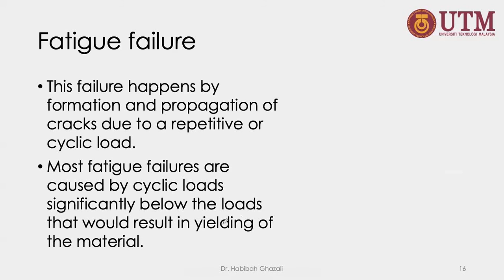But for cyclic load, for example, a timing belt, your car service. The engine keeps rotating round and round, isn't it? Cyclic load. So there is a limit. After 100,000 kilometers, there is some service. The kilometers indicate the cycles. They know after this number of cycles, the material will fail, even though the design is safe.